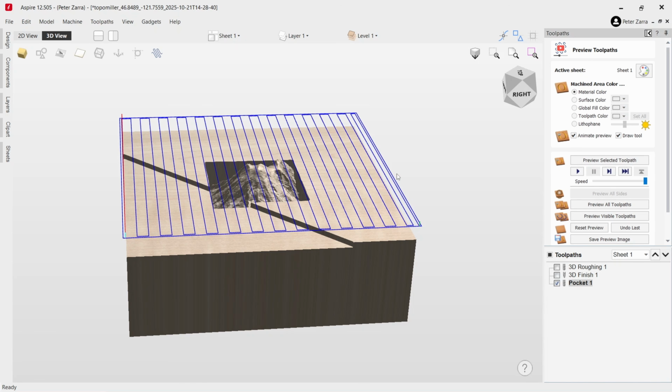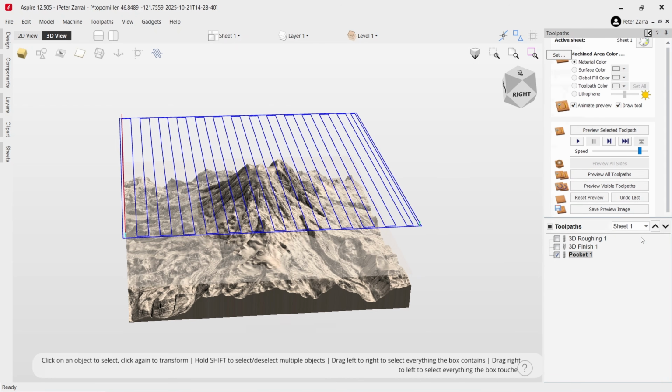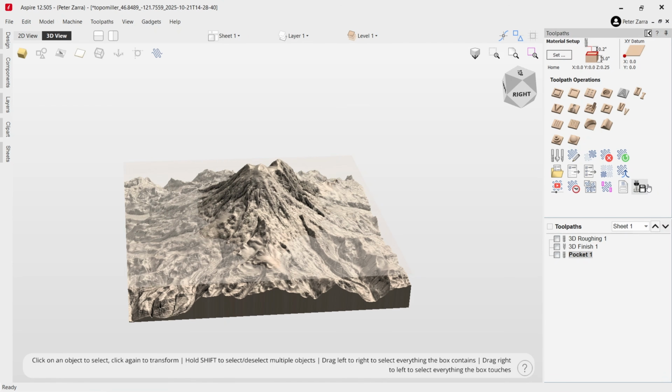So now you have a surfacing toolpath that you can use to surface either individual layers as you're gluing them up beforehand, making the block, or once you have it in place and you want to surface the bottom or the top, you now have a surfacing toolpath for that. Okay, so then from here, you would just go ahead and individually save your toolpaths to your files there, and you're all ready to go. It's really, really simple to do, and you can design one of these in 10 minutes. It's really a piece of cake.